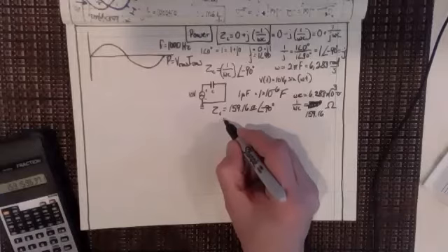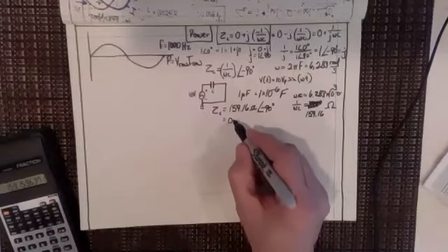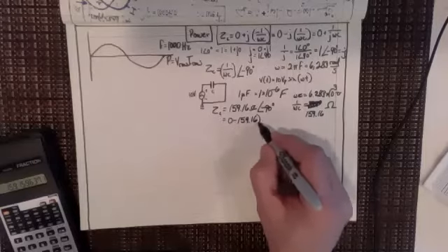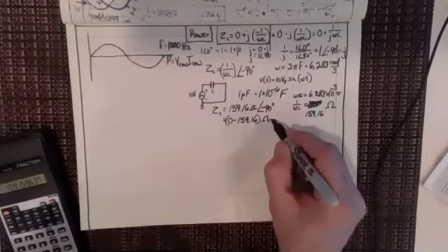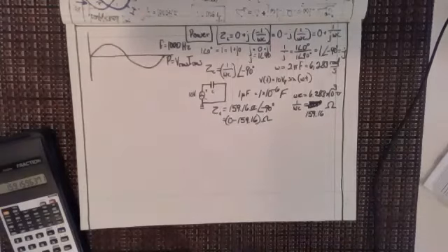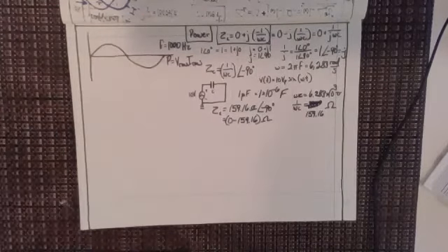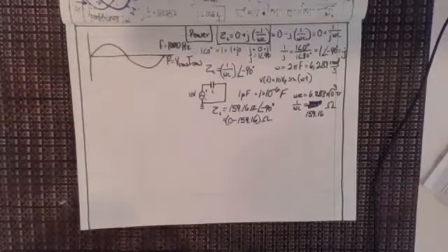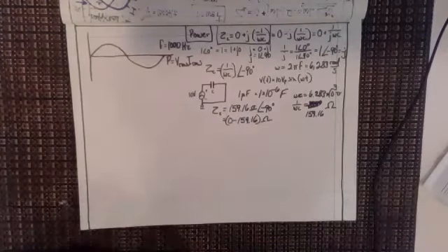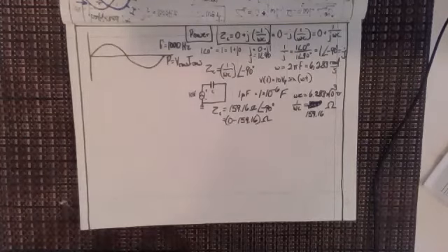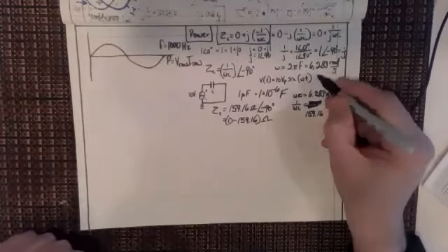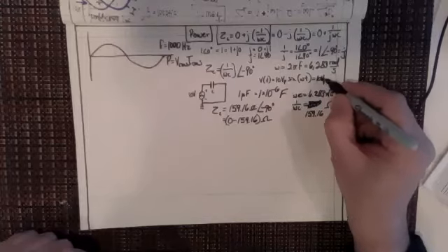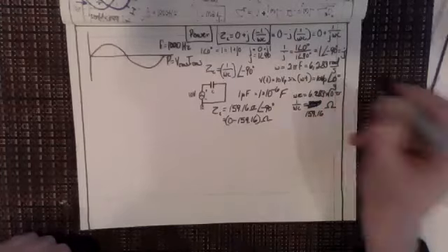I could also say that it was 0 minus 159.16 ohms if I was writing it in the rectilinear, the a plus jb complex number notation, right? So either way. But we're going to be dividing or multiplying, so we want to use it in its phasor form. And we've already got V in its phasor form too, 10 volts peak at 0 degrees, right?